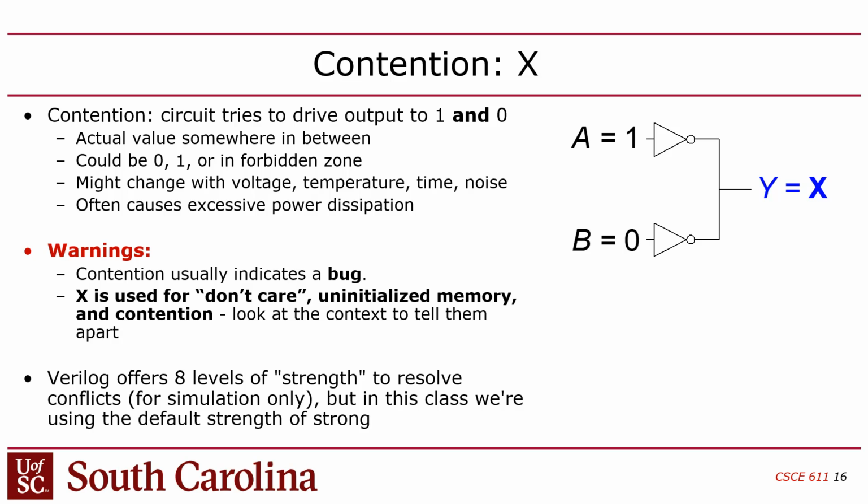So if you have two logic gates that are both connected to the same wire, and one of them tries to pull up and the other tries to pull down, they're in contention. What's really happening is that one is creating a path to VDD with a 1 ohm resistor, and the other is creating a path to ground with a 1 ohm resistor. So you end up with a 2 ohm equivalent resistance between power and ground. You've basically shorted out the power supply, right? Now, you might say, well, what happens? Does it explode?